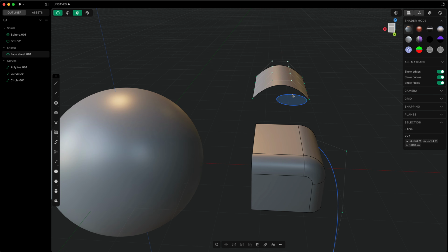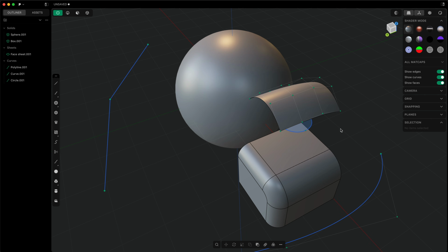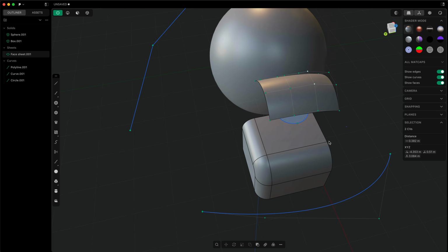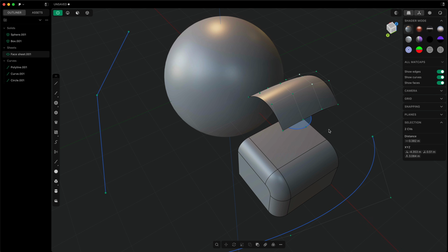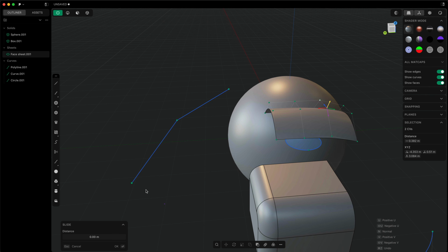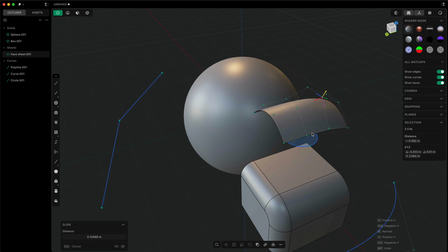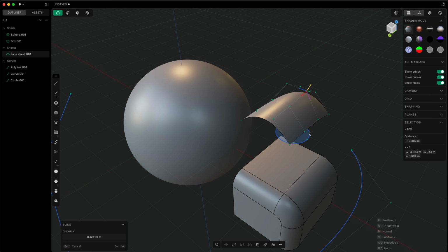One of the most important surfacing tools in professional surfacing packages like Alias is the ability to move CVs along their UVN coordinates. So we have a new command called slide, which allows you to move CVs either along their hull or along the local normal. And this allows you to work off axis as well as add things like crown very easily.